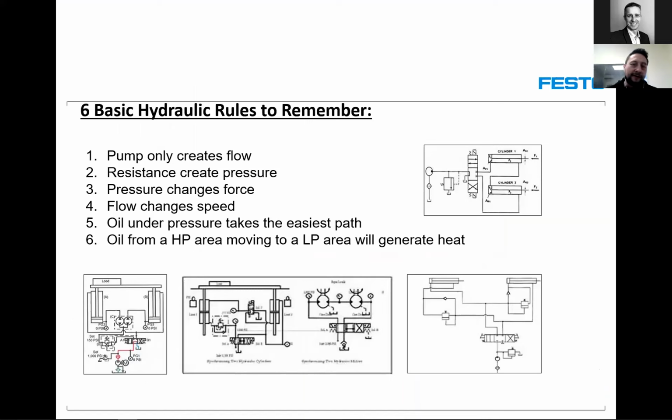If you block anything on any line in a hydraulic system, and you do not have safety on that system, something will happen, and what will happen is that something will break. So if your pump is the weak point in the system, your pump will break. If your piping is the weak point, then your piping will break. If you have anything else in that line, whatever is the weak point in that line will actually break. So when you overpressurize a line, it's not good practice.